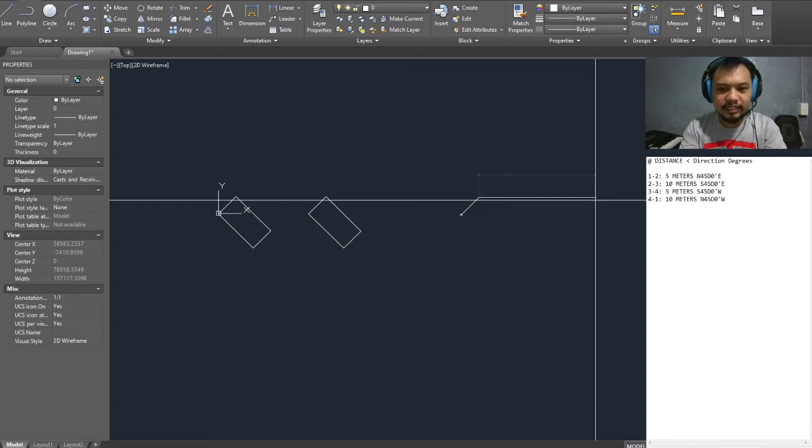And then we're going to use at 10,000 angle symbol. In this way, we know that it's going to be negative. We can also use the minus symbol, which will make it negative 45 degrees, or we can actually compute it ourselves. So we know that this will be 90, 180, 270, 315. So we'll put 315 degrees there. See, no problem. And then we're going to say at symbol again, 5,000 millimeters.